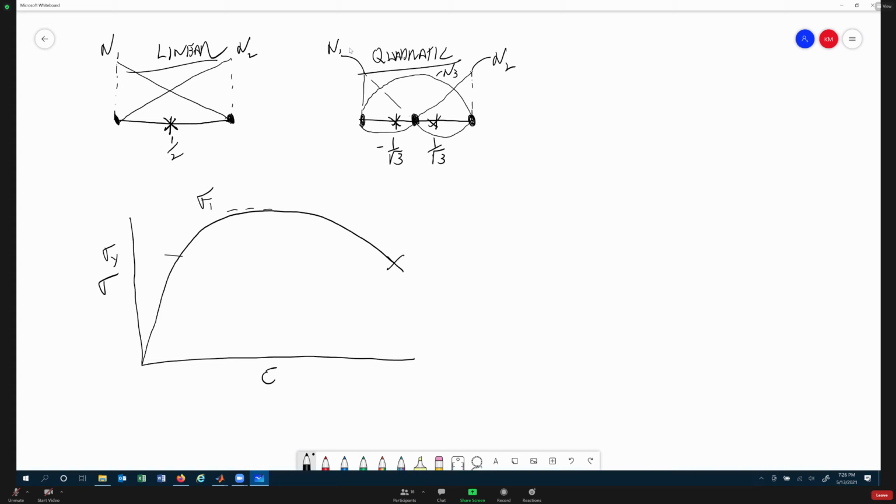If we wanted to represent this line in a linear fashion, like a piecewise linear, we could break this up into linear points, right? You can go from here to here to here to here. I'm exaggerating being off the line because my artwork is horrible. And you see it gives us a similar approximation that we had with our exact solution with our FE solution when we had a low number of elements and a linear approximation. So it's basically the same thing as when we're doing this linear. It's almost like a piecewise linear fitting function that you're doing to an exact solution.